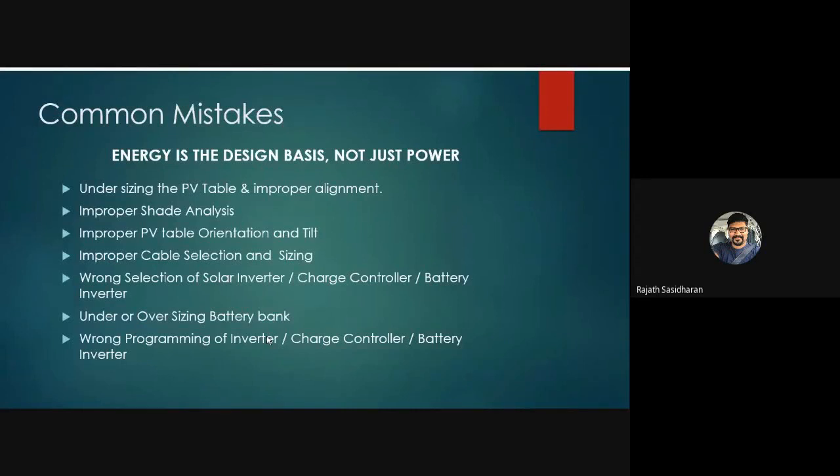If you undersize the battery bank, there will still be excess energy from the MPPT, but there is no provision to charge the batteries any further. So the MPPT will just stop generating electricity. So that's a waste of energy there.